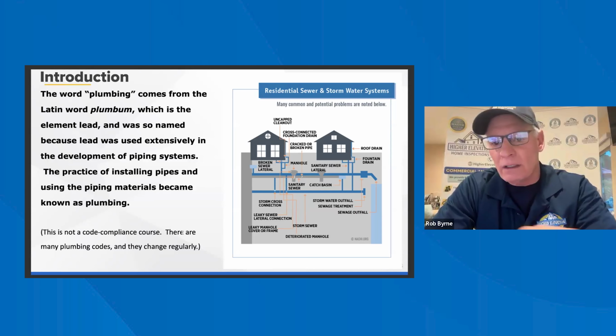Access. Water heaters should be accessible for routine inspections, maintenance, adjustments, repairs, and replacement. Manufacturers usually make access recommendations. Access means to be able to reach the water heater by possibly first removing a panel, etc. Accessible does not include or imply the removal or destruction of finished materials, drywalls, etc.